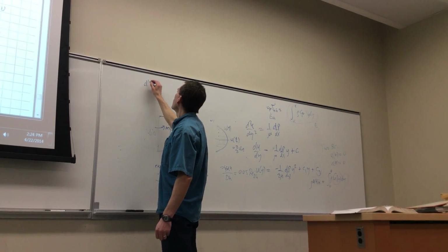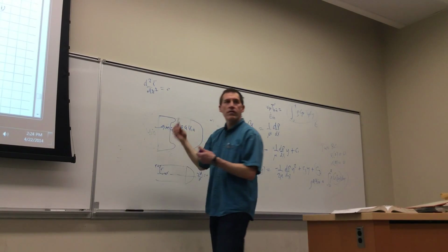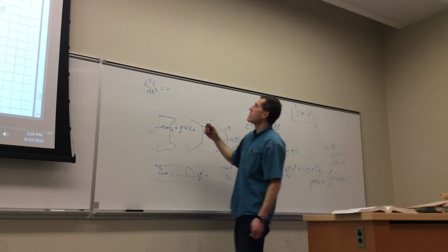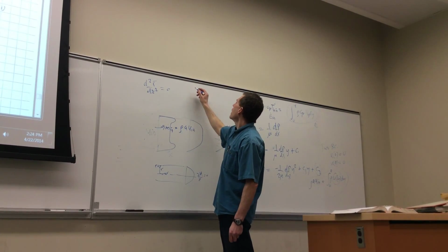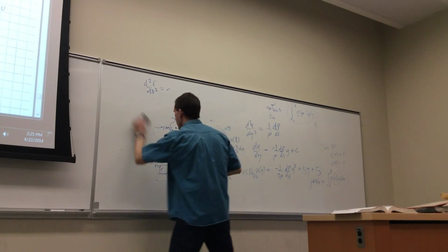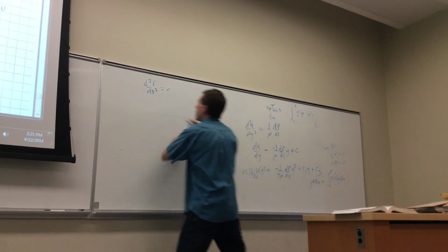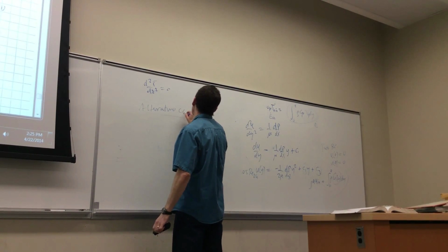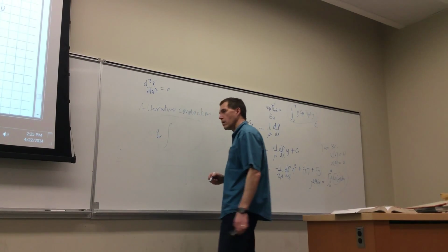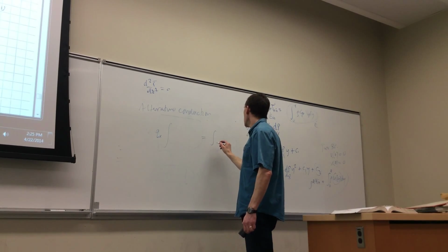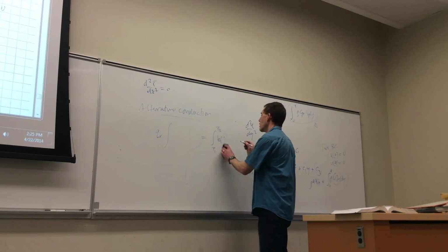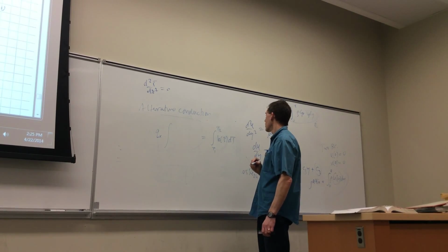We had d2T/dx squared equals 0 and integrate twice for a solution for that. If you had d2/dy squared, you integrate twice for that. What else did we have? For the alternative conduction, we had q of x times what? Equals the integral from T1 to T2 of k of T dT. Is that right?